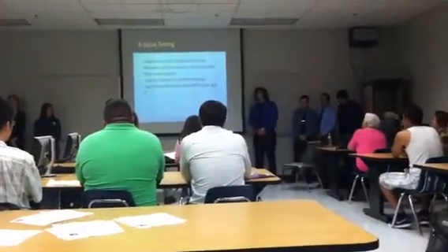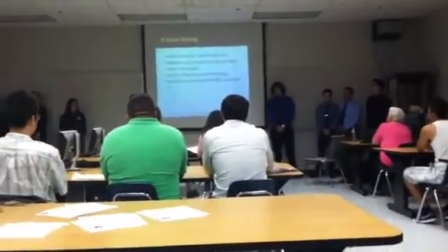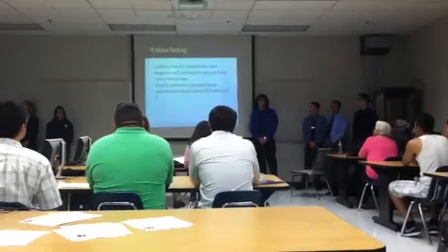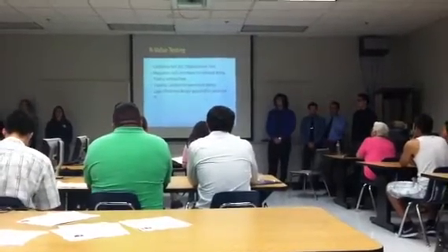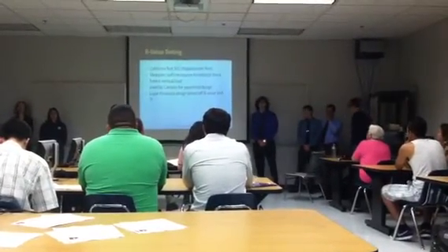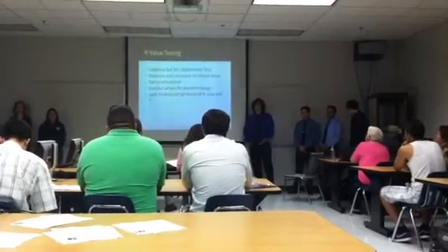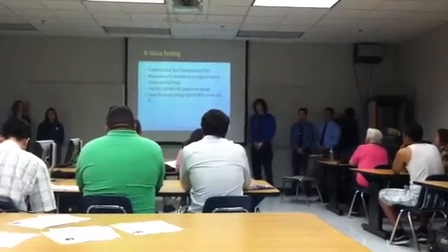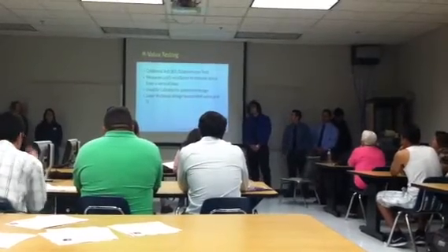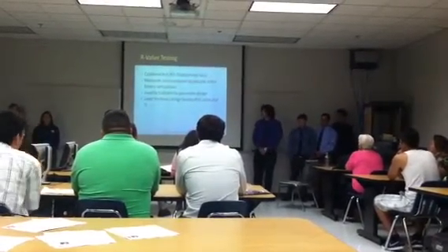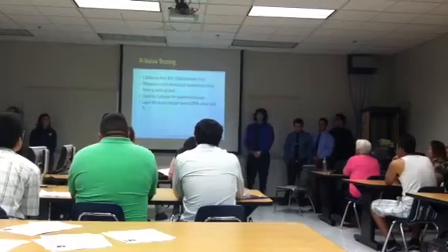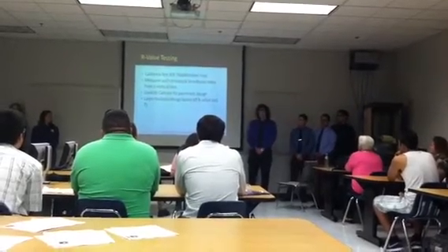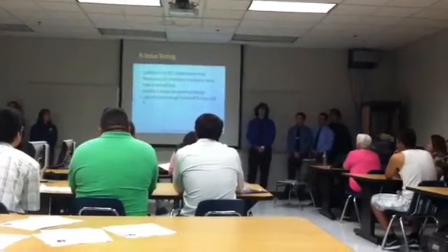Next, I'll be talking about the R value. To get the R value, you have to perform what is known as the California Test 301, otherwise known as the stabilometer test. What this test does is it measures the soil's resistance to an induced stress from a vertical load. This test is fairly popular in many industries in California, especially in Caltrans. The layer thickness is designed based off the R value and the TI.